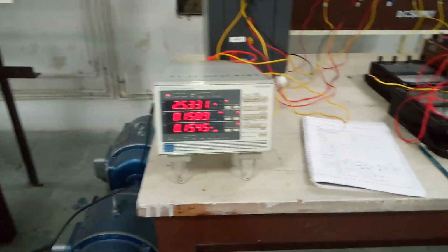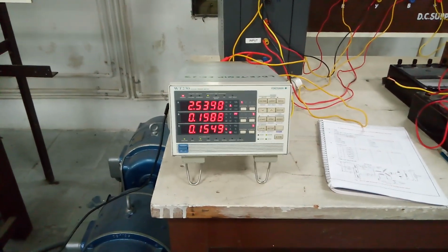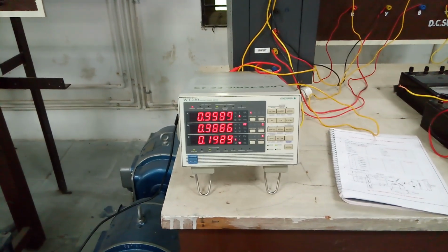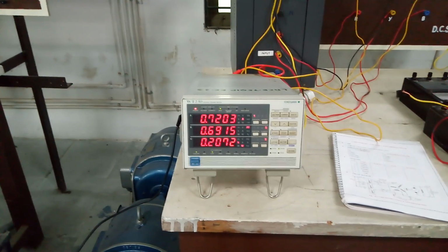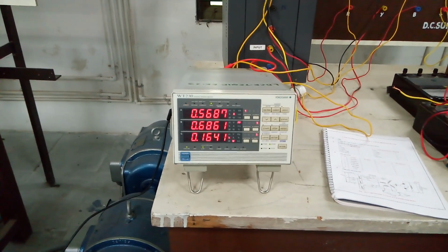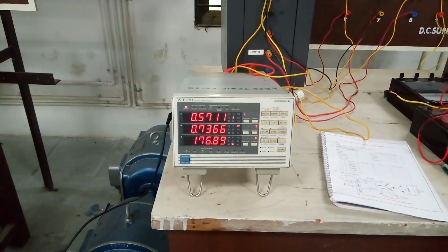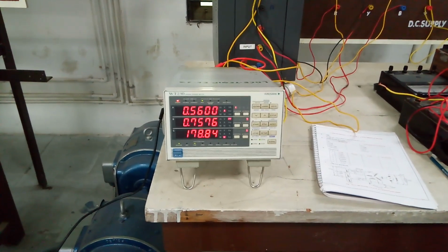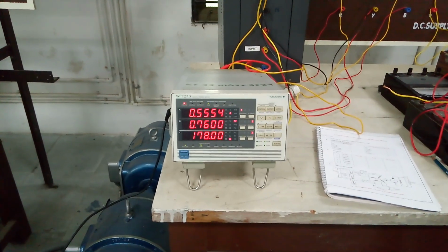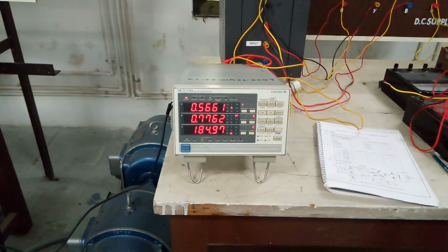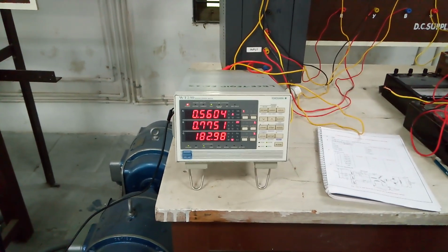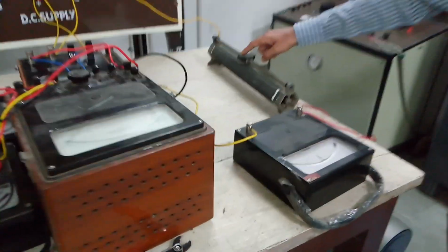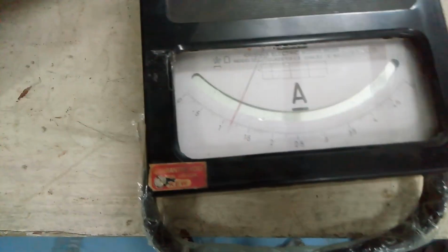Now I am going to change the position of the switch and apply the DC. The current earlier was 2.5 ampere; no doubt it takes some time to settle down. Now you can see the current, right? So that is the effect of excitation on the current. Somebody might be thinking, sir, why is there this jump? Because right now we have adjusted our field winding to the middle position, our field setting almost, right?